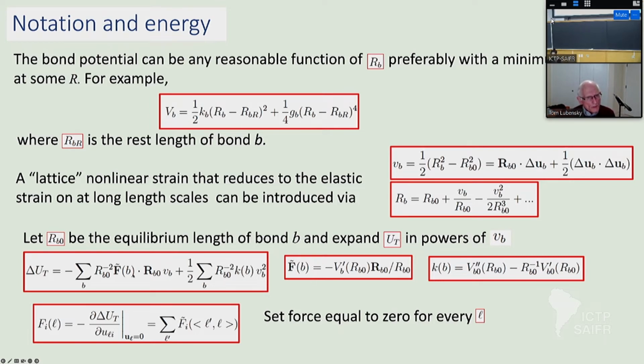This term is actually a residual term from possible stresses in the bonds that occur if we have states of, well, I haven't done states of self-stress yet, but this is having tensions in the bond, but an equilibrium lattice anyway. So you can see I have a force dotted into a displacement divided by an area times an area, and this thing has the units of force times distance. And it wants you to think about the stresses being a force crossing a plane, and there is a distance that is between the neighboring points.